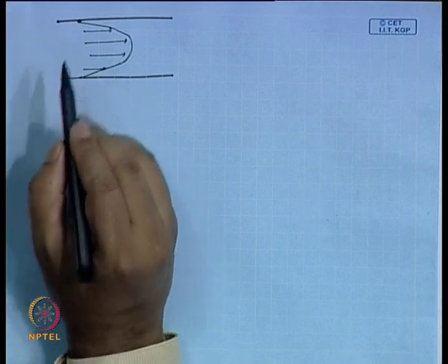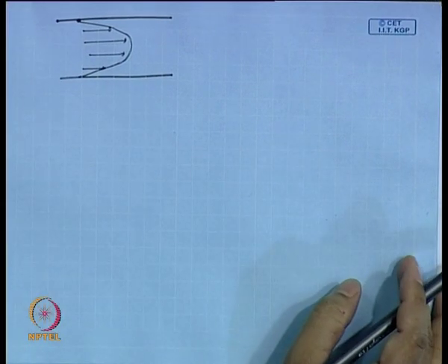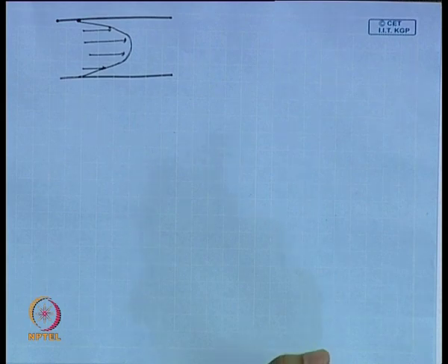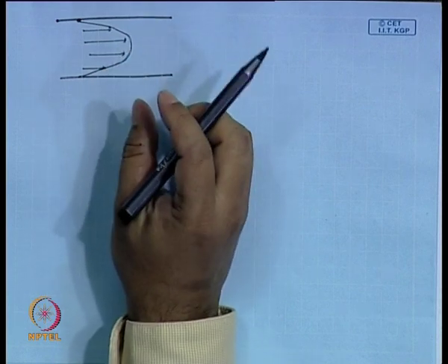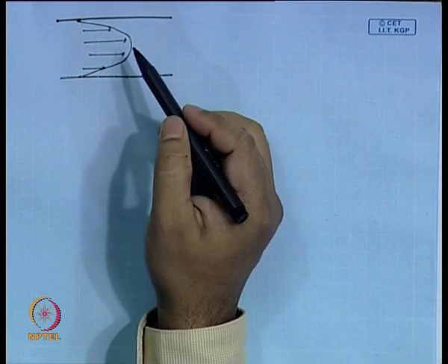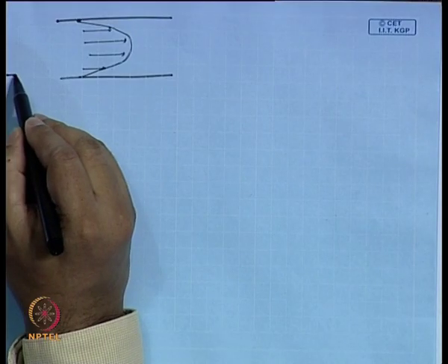So, this Taylor dispersion, mind it, is important in a micro channel when the transverse dimension is small. If it is a big channel, I mean a large diameter channel, absolutely this is not at all a problem, because there you will have a potential flow. I mean the effect of viscosity would be less, it would be a potential flow at the center. Okay. So, this problem may not be important at all. Suppose this is a parabolic velocity profile and you give a pulse.